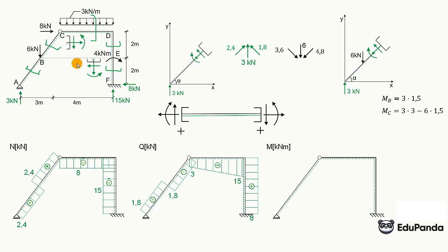So now we know everything. 4.5 in the middle, 0 at the end, linear function. Now we start on the vertical beam. Looking from the bottom, do we have any initial moment? It could be, but here, it's rare actually, but here in this fixed support, it turned out to be 0. The fixed support moment came out to be 0, so no initial moment. So, just like on this sliding support, we will have an initial moment of 0. If there was any moment, we would start from its value.